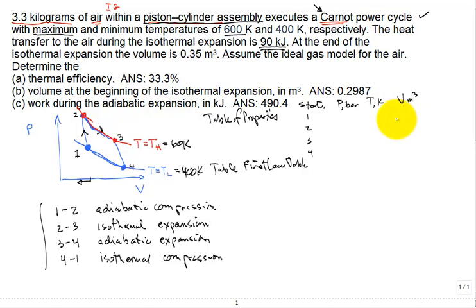And then you could have other properties, let's say internal energy in kilojoules per kilogram. Now, having solved this problem before, that's all. Sometimes you don't know what you have, and maybe you need to put quality, but it's air, so air is not going to have a two-phase mixture. But if it was steam or refrigerant, quality may be in the table, or enthalpy. But I just know that these are enough for this problem.